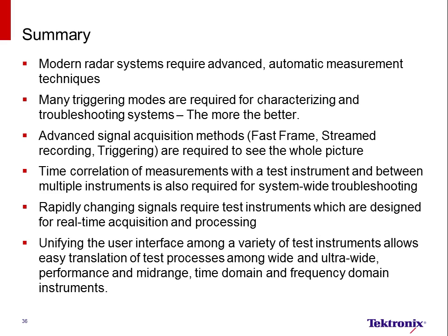Time correlation of measurements with a test instrument and between multiple instruments is also required for system-wide troubleshooting. Rapid changing signals require test instruments that are designed for real-time acquisition and processing. Unifying the user interface among a variety of test instruments allows easy translation of test processes among wide and ultra-wide, performance and mid-range, time domain and frequency domain instruments.